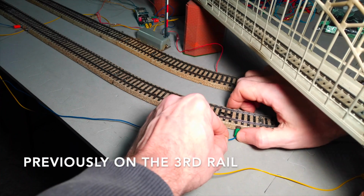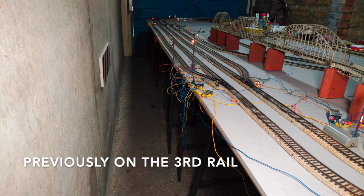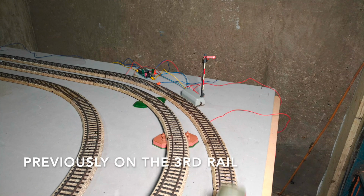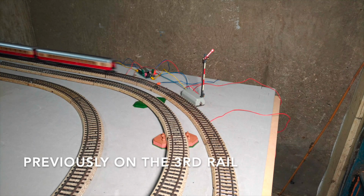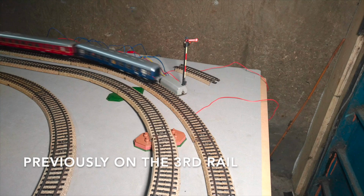And after laying a few meters of wires, I was soon able to do a first test with 2 locomotives. Further tests with longer consists soon revealed an issue of timing in the block leading to the station. So I had to install an additional circuit and a universal remote switch in order to resolve it.